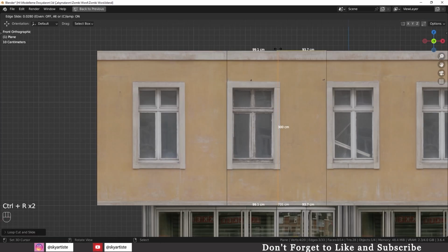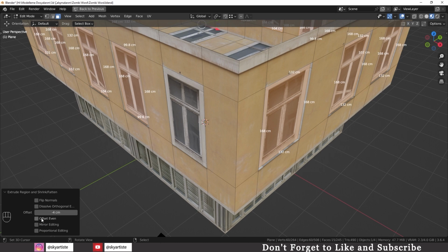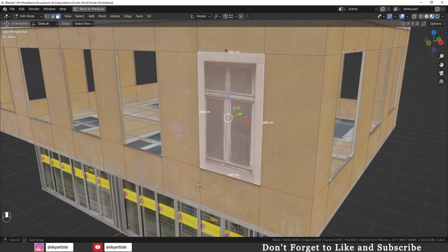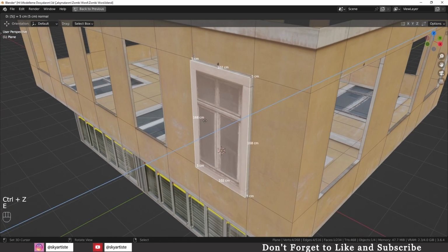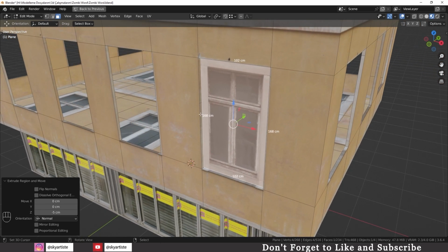We determine the window gaps with loop cut. We leave one window and select other window parts and extrude inwards. We wipe the glass parts where we made the extrude. We leave one window behind. We select our only remaining window and extrude 5 centimeters inside.